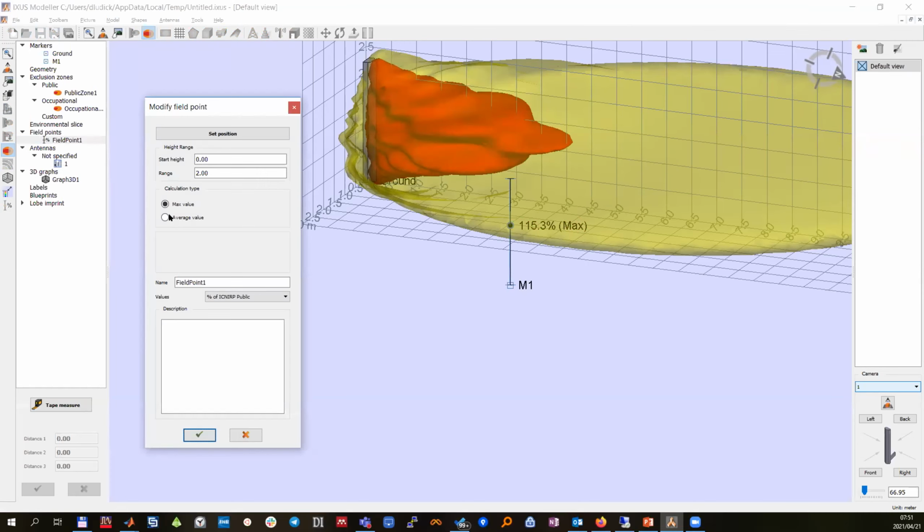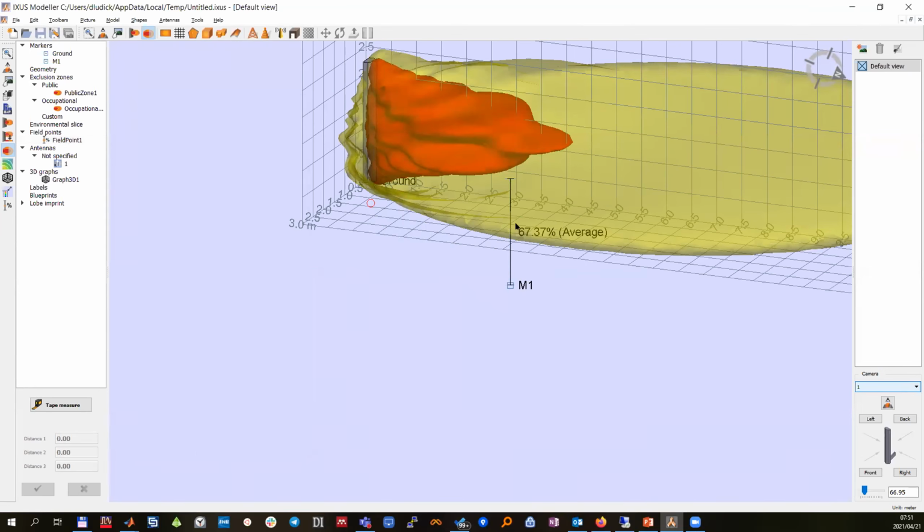So likewise, I can now switch to an averaging scheme and I can say, okay, I want to average at 0.1 intervals here, and this will result in 21 sampling points. And then I can run it again and my results are returned as a percentage, but here I can clearly see that it's the average. And there's no particular point because the average is applied in this entire region.